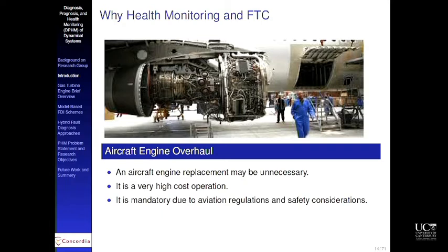or time-based maintenance. It doesn't matter how I drive my car, whether the car is driven in the desert, in the North Pole, wherever, it's fixed. The manual comes with a set of instructions, and we all follow it. Well, what's the problem with that? The problem is that you may not need to change the oil, because I was operating in a tropical environment, so there was no pollution, nothing like New Zealand.